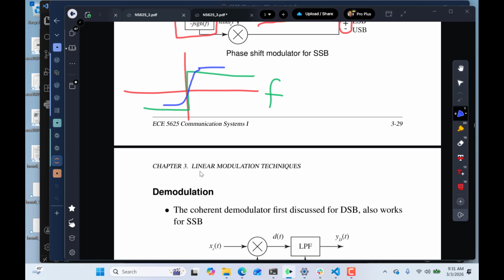And then it carves out a little bit of the frequencies close to DC, either on the negative or the positive side. In classical amplitude type modulation or linear modulation applications, it's okay for speech to not have DC. We don't convey information, and we don't have super low frequencies we care about preserving in our speech.